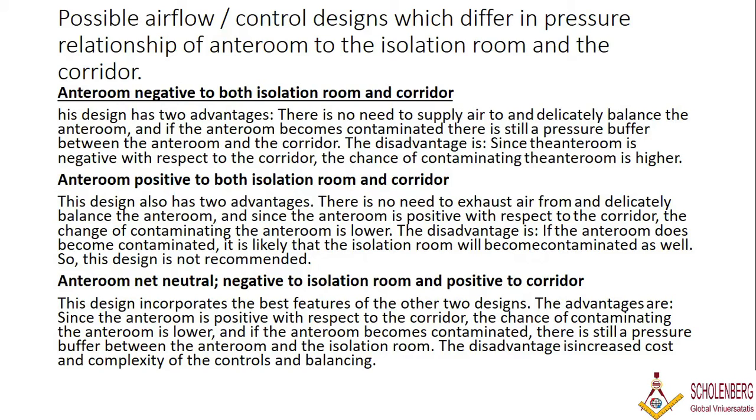This design has two advantages. There is no need to supply air and to delicately balance the anteroom. And if the anteroom becomes contaminated, there's still a pressure buffer between the anteroom and the corridor. The disadvantage is that since the anteroom is negative with respect to the corridor, the chance of contaminating the anteroom is higher.